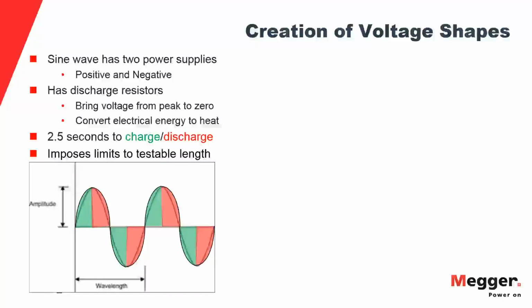And just so you don't accuse me of lying to you, it is important to note that this is an idealized condition. I have these cosine rectangular and damped AC represented as exactly 60 hertz. It's very unlikely you'll ever see that. But the idea is to illustrate the point that they're in the same frequency range as power frequency. Again, both of these technologies operate in the 30 to 500 hertz range, which is in the power frequency type of range.